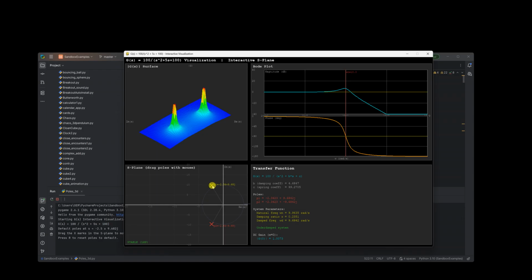But what I did here is I can vary them, and so I can move them around. I actually didn't put the step response. I should have put that in as well. I could still do that, but I'm looking at the frequency response. So as I get nearer the j omega axis, you should see the resonance, see how it goes up to infinity at the j omega, and look how the phase shoots down to minus 180, very sharp phase.